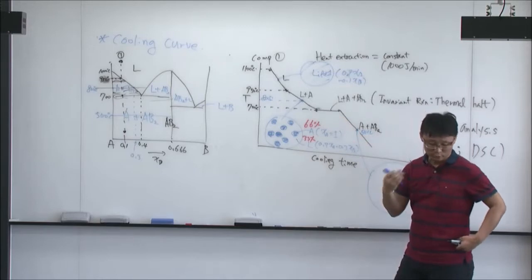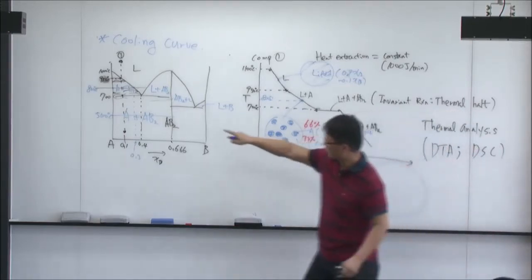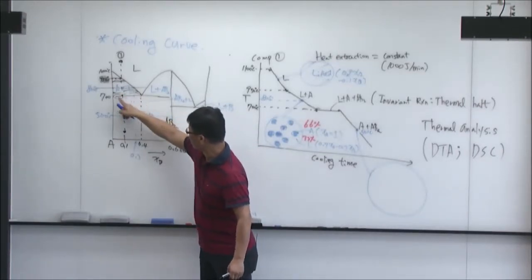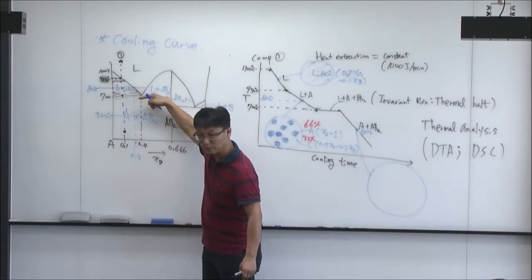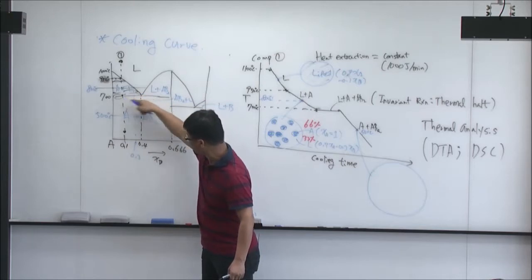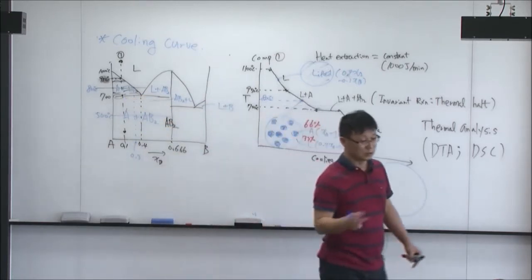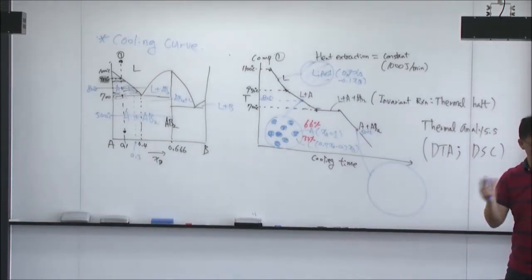Okay? So during the eutectic reaction, we originally have all solid phase. So the amount of solid phase here is this divided by the entire length. So at the eutectic point, just before the eutectic reaction, we have 0.3 divided by 0.4 of the solid A. So it's 75% of the A solid and 25% of liquid remaining.